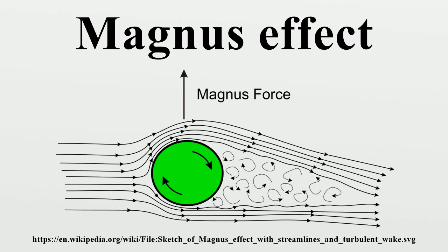The process by which a turbulent wake develops after the body in an airflow is complex but well studied in aerodynamics. It is found that the thin boundary layer detaches itself from the body at some point, and this is where the wake begins to develop. The boundary layer itself may be turbulent or not. This has a significant effect on the wake formation. Quite small variations in the surface conditions of the body can influence the onset of wake formation and thereby have a marked effect on the downstream flow pattern. The influence of the body's rotation is of this kind.